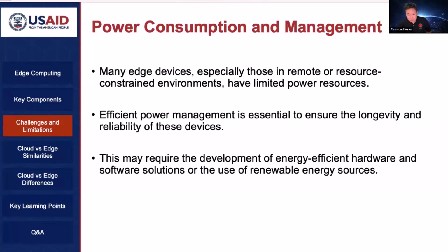And as we know, with battery, no, the environmental temperature also affects the amount of power it could store. So we need to factor all of those and provide the appropriate battery solution. And we also know that over time, the capacity of batteries diminishes, no? So it depends on how long we expect this device to live within our project. We would need to mix and match basically power source and power storage.